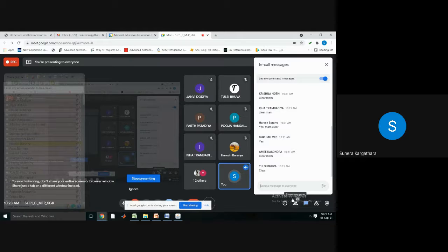You need to go and compare. Suppose I have designed a counter which will count from 0, 0 to 10, right? So 0, 0, 0, 1, 0, 2, like this, incrementing, I will reach 10. So I need to compare my present count with my predefined value 10. Are you getting my point? If it reaches the final count, then it should stop. If it is not, then go and increment. So that can be one way to design a counter, which is an up counter.